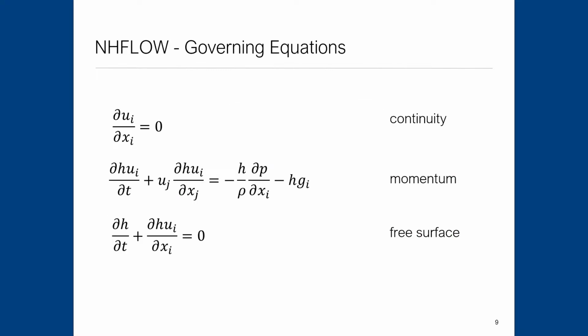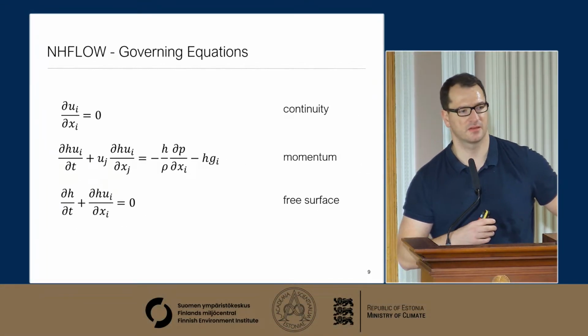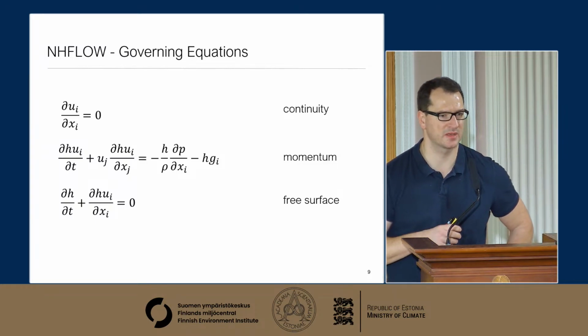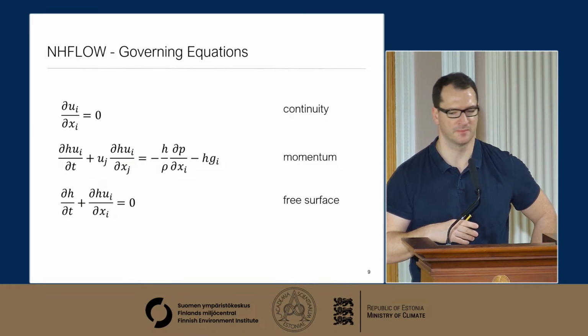Yeah, I'm just showing here the governing equations. So for this new model, NHflow, a non-hydrostatic model, we're solving the full Navier-Stokes equations, continuity, momentum, and then the free surface elevation is being calculated by integrating the continuity equation over the depth.